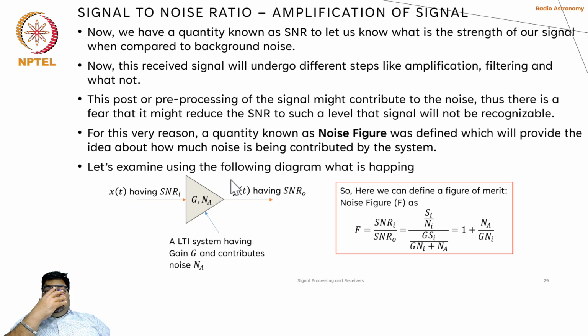So before sending the signal through the cable, the typical thing is to amplify it. Amplification itself comes with a cost, in that some noise could be induced by the electronic component itself. So the first thing is choosing a low noise amplifier. The second thing is choosing a cascade of such amplifiers to give a higher gain. We'll talk about it now.